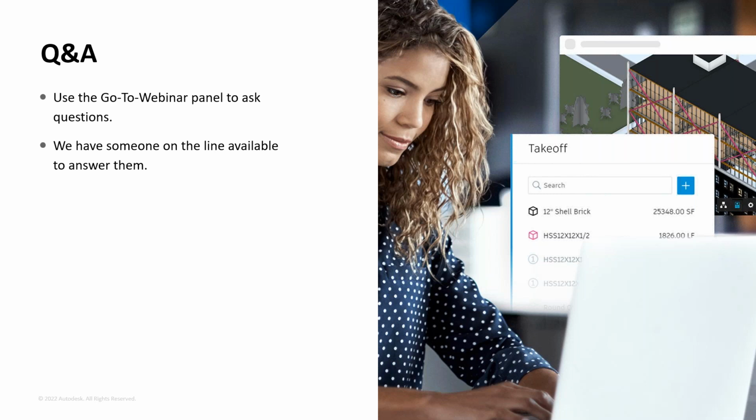Another question that I see here is, the inventory export used to give added up sums of similar takeoff types. Now I have to manually add all sources of any same takeoff type myself. It adds a lengthy, repetitive step. So essentially, when you do go through and you develop those different takeoff types, you can organize them in different manners. So if you organize them based on classification type, you could then easily go through and have that sum up. Same way, you could also organize things by location or something like that, so that way your quantities will sum up there as well. And then I would maybe evaluate the different ways that you guys are developing takeoff types. So if you have a lot of standard walls that you want to be taking off, you can organize those together to have those quantities sum up as well.